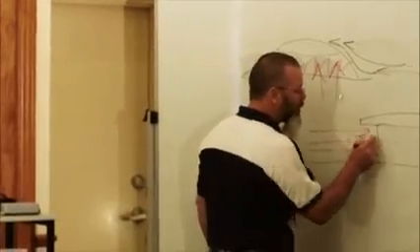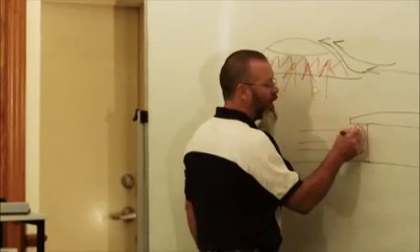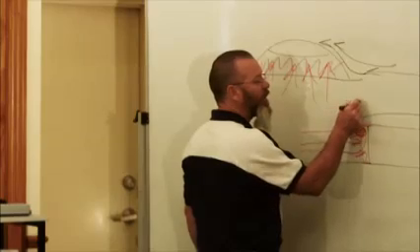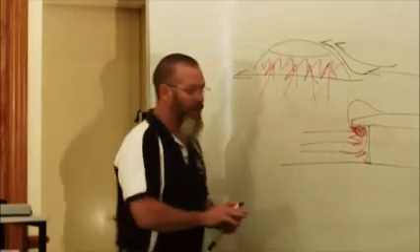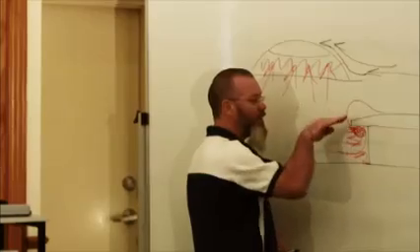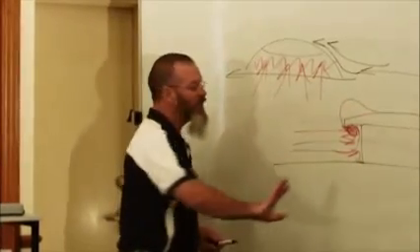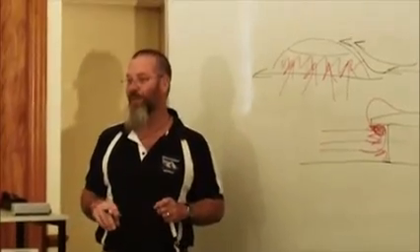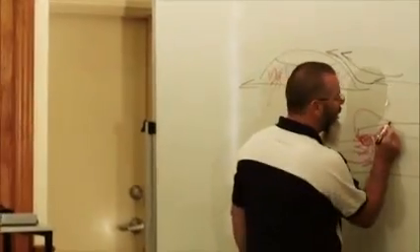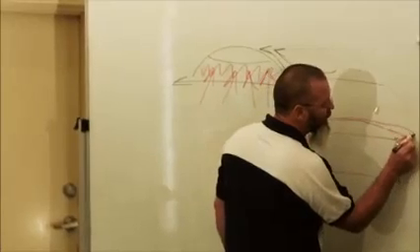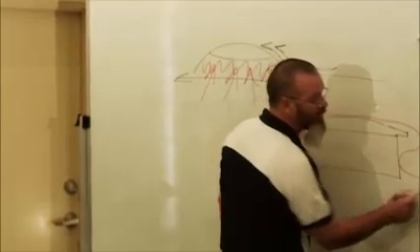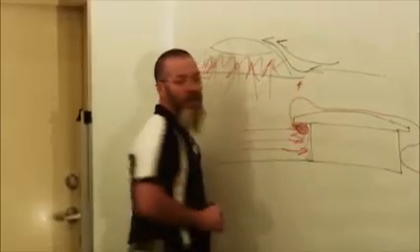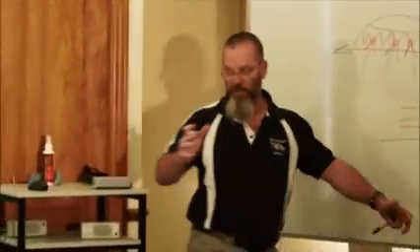So what actually happens is it all compresses and it comes up here underneath the eaves till it reaches a point where it's compressed and it comes up and it does this. Again, as I said, the wind doesn't come out and go just 90 degrees and back across. Because of this viscosity, it forms this, and I use the term loosely, Bernoulli bubble at the outer edge here. Then it comes across here and it does the same again, creates a Bernoulli bubble at the side of the building. So what you're getting here is an uplift at that point, an uplift Bernoulli bubble.